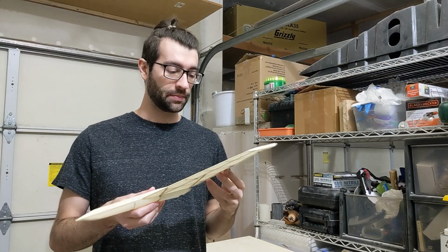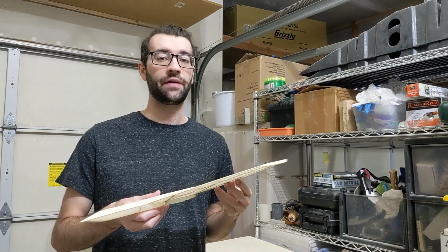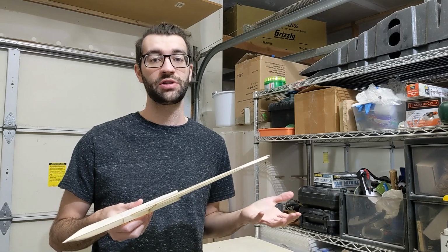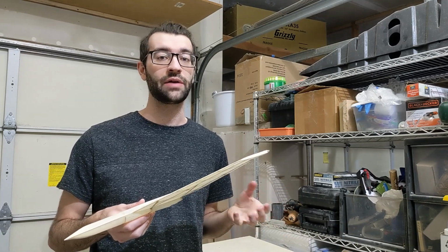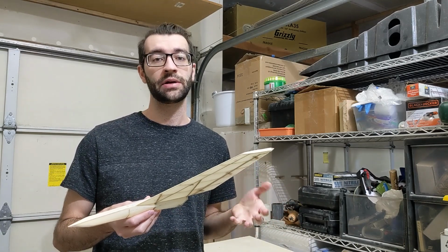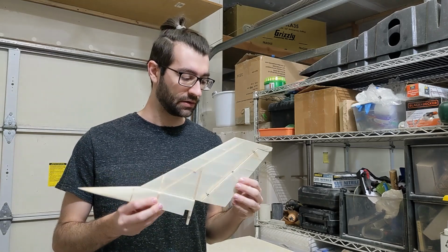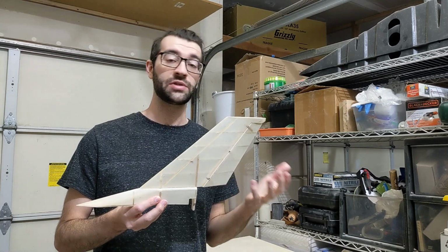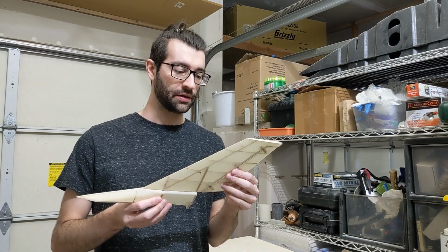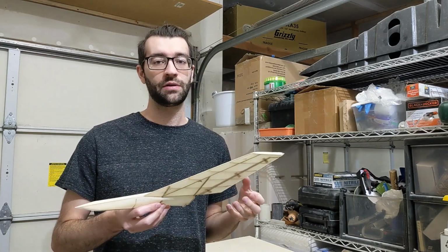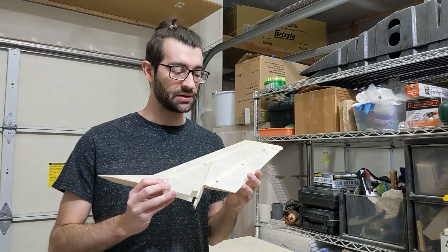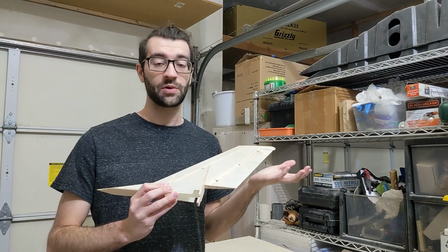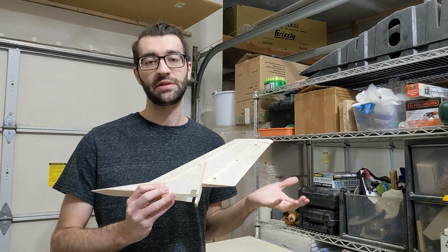Okay, so unfortunately the parts are ending up a little bit heavier than my estimates, but then again, that's not too much of a surprise because my spreadsheet, again, is just an estimate and it doesn't include every single part that is going to be on the airplane. For example, on the vertical fin, my spreadsheet isn't considering the hinges that I have inserted, so those add a little bit of weight too. But I think the biggest contributor to these parts being heavier than my estimates is the epoxy that I was using to bond all the internal structure to the skins. In the spreadsheet, I didn't have anything to compensate for that.